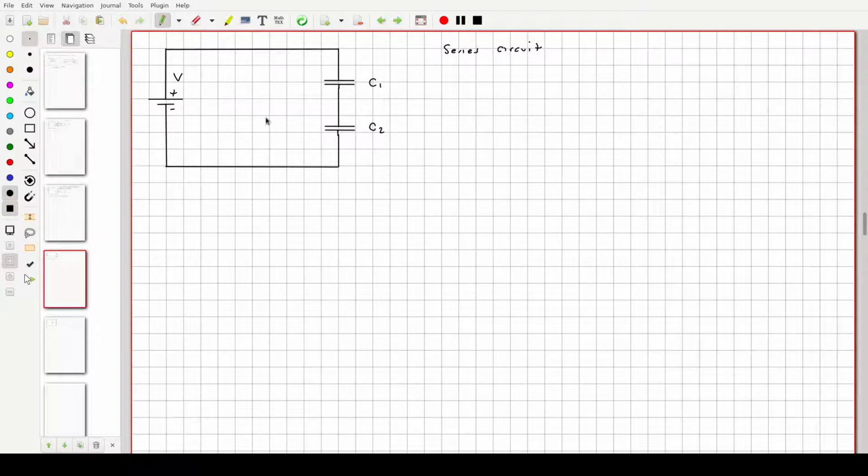So if I follow the equipotential rule and think of this wire as a region of equal potential, then whatever voltage is here is the same voltage that sits here. Now, the way a capacitor is drawn is deliberate. There's nothing that sits between the plates. There's no direct connection between this side of a capacitor and this side. It has to go through a battery or some other component, at least as drawn.